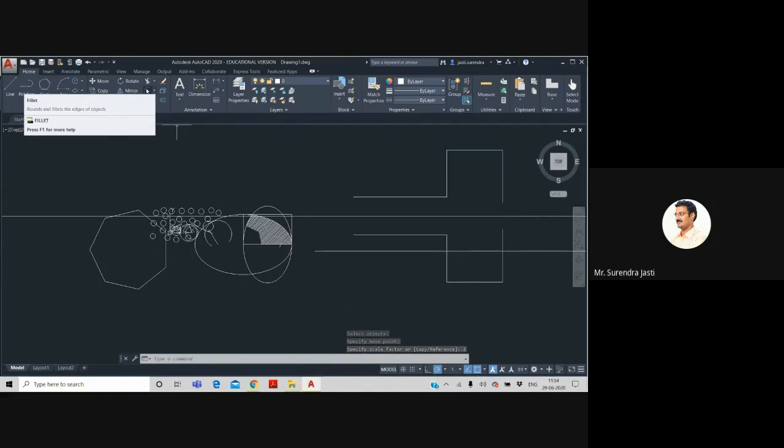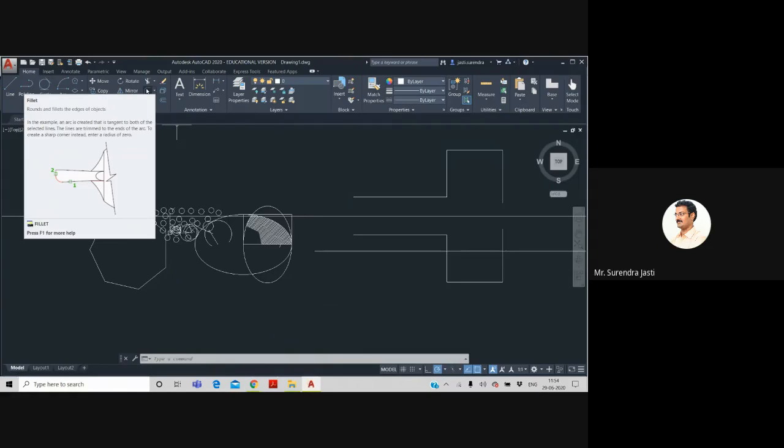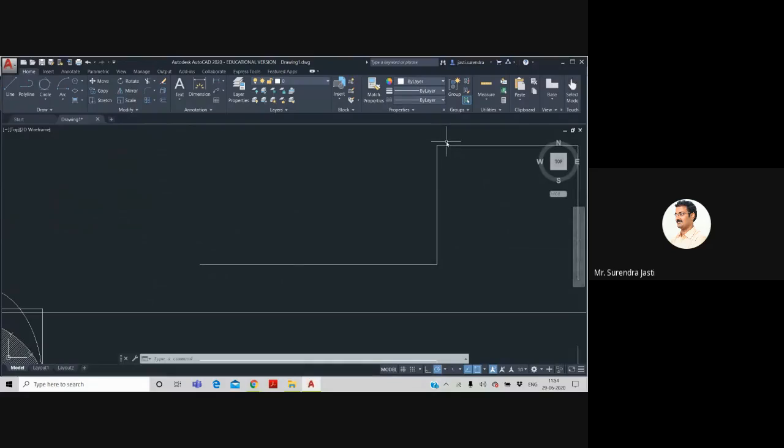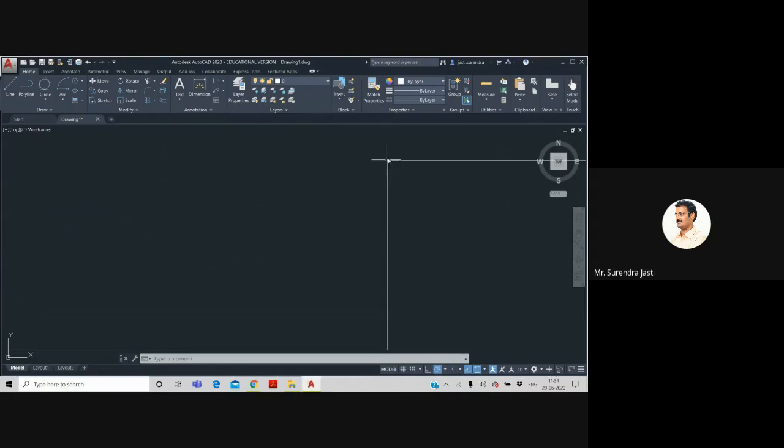And this is the fillet. Especially for mechanical students, filleting is important in any component. Suppose you want to reduce sharp corners for safety purposes. In most situations, any component has sharp edges like this. Sharp edges are not preferable, because they are not safe. Even in stress calculations and other calculations, we try to eliminate these sharp corners. To eliminate a sharp corner, we draw a small arc with a 3 to 5 mm radius. This is called filleting.